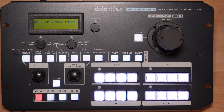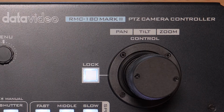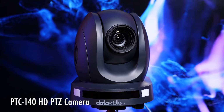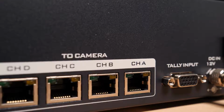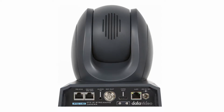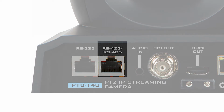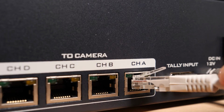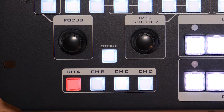In this video, we're going to go over how to control and operate the Datavideo PTC-140 from the RMC-180 Mark II camera controller. So first, you'll want to connect the PTC-140 to the RMC-180 Mark II using an Ethernet cable connected using the RS-422 port on the back of the PTC-140. Connect that to either channel A, B, C, or D on the back of the RMC-180 Mark II camera controller, depending on your setup. So we've connected our camera to channel A.